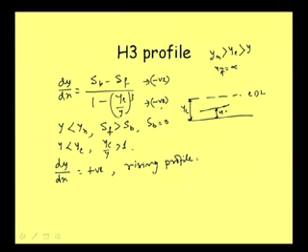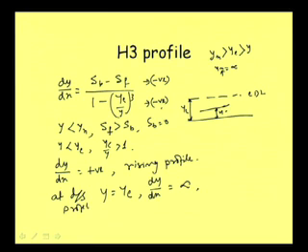Once we get the profile to be a rising profile, then at downstream y is equal to yc. So, this will indicate again dy/dx is equal to infinity. So, the profile meets the CDL normally. Okay, so we can draw the profile like this.